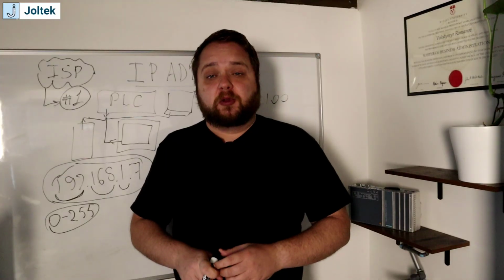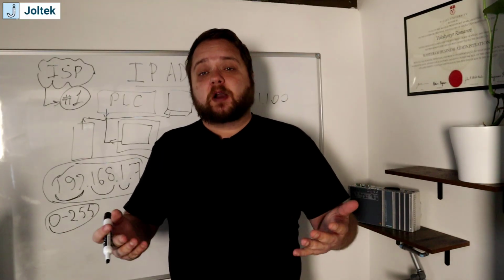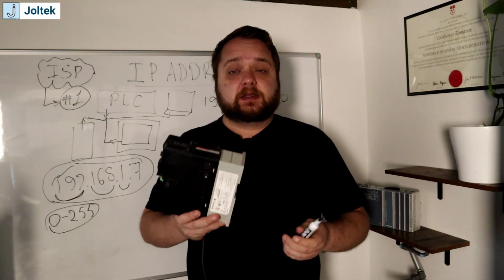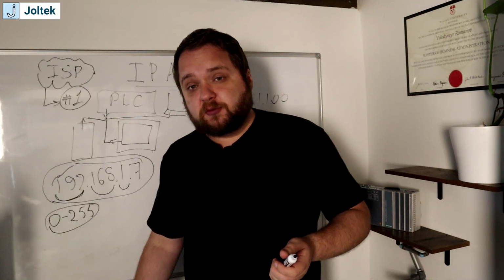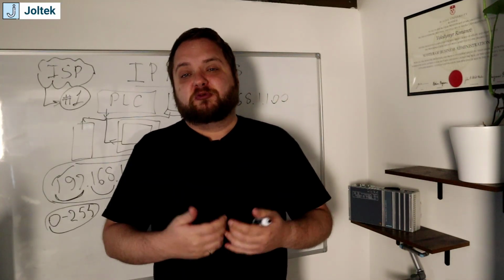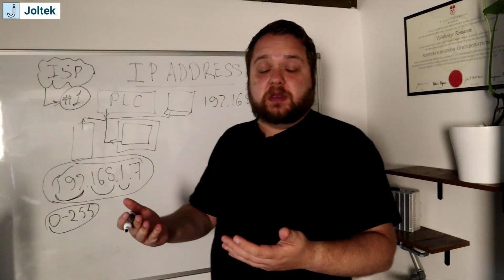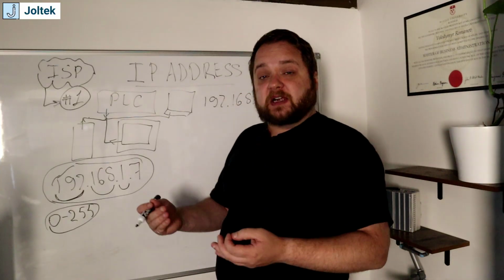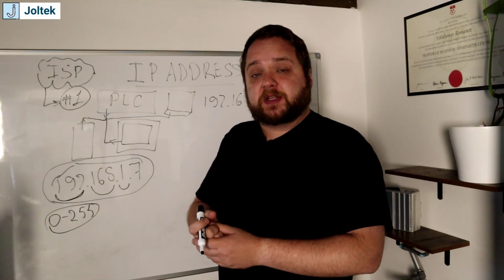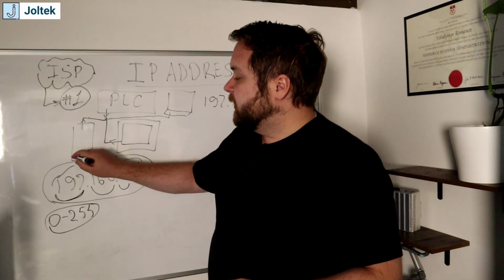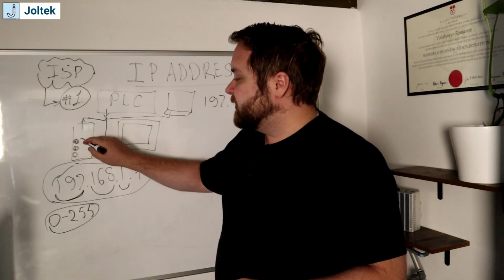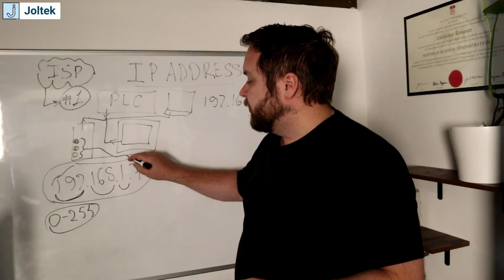And to give you one example in terms of practical OT knowledge, a lot of the Allen Bradley hardware, so not including the PLCs and some of the VFDs, but when you look at, let's say, Point I/O or Ethernet cards that you will find on the control logic side, you will typically find a set of dip switches. And if you read the data sheet, a lot of times what can be done if you don't have access to the software, right, that's going to be BOOTP or RSLinx or via the web page for that specific card, what you can find is, like I said, a little set of dip switches. There's going to be 3 of them that allow you to basically set the IP address, and that's going to be only the last octet, right?